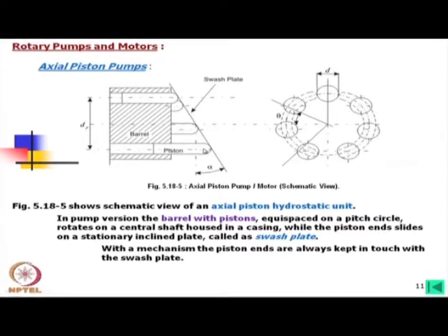Now, another point is that, say for example, suppose this is being used as a pump. The suction side means this piston is moving in this direction, right hand direction. So, what is the guarantee that the piston will move with the swash plate?